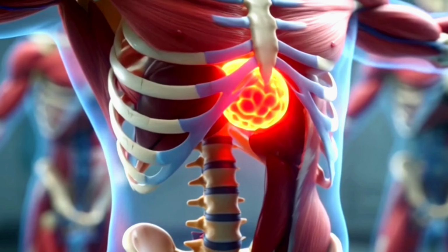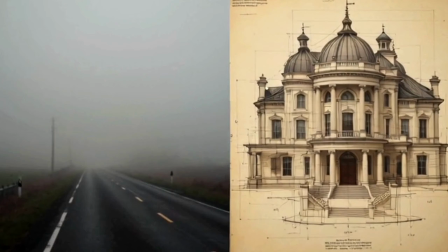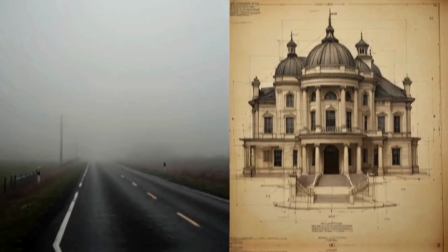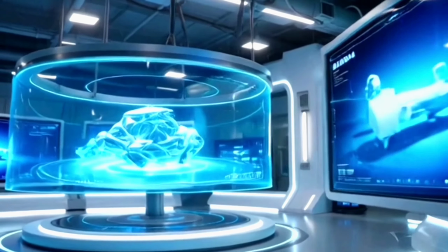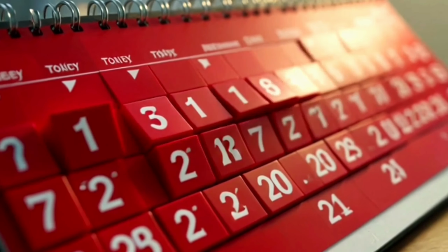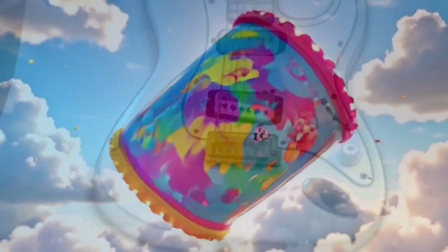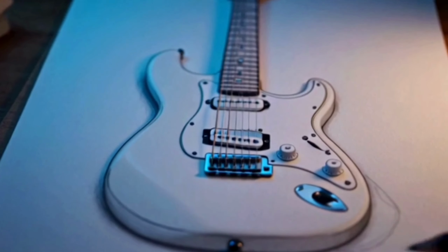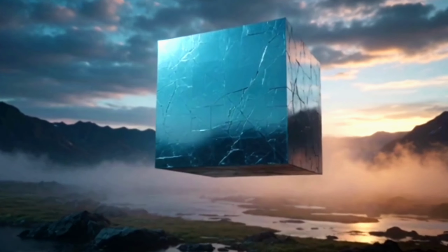Precision starts with the cutting plane line. In your top view, draw a thick dashed dot line through the center of the hole and the rib. Add arrows pointing toward the front view. These arrows tell the viewer which direction we are looking. Now, let's refine the projection method. Vertical alignment: every feature in your top view, the 75 mm base edges, the 12 mm rib walls, and the 12 mm hole limits, must align perfectly with the front view above it.